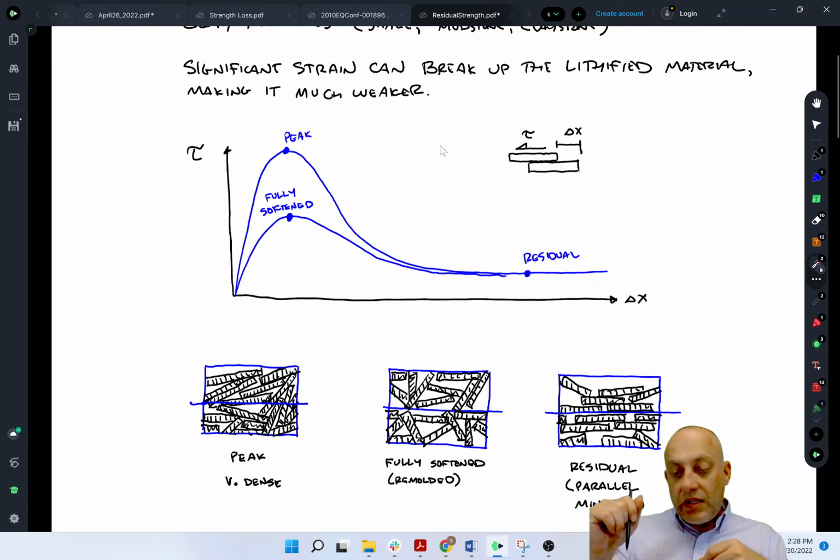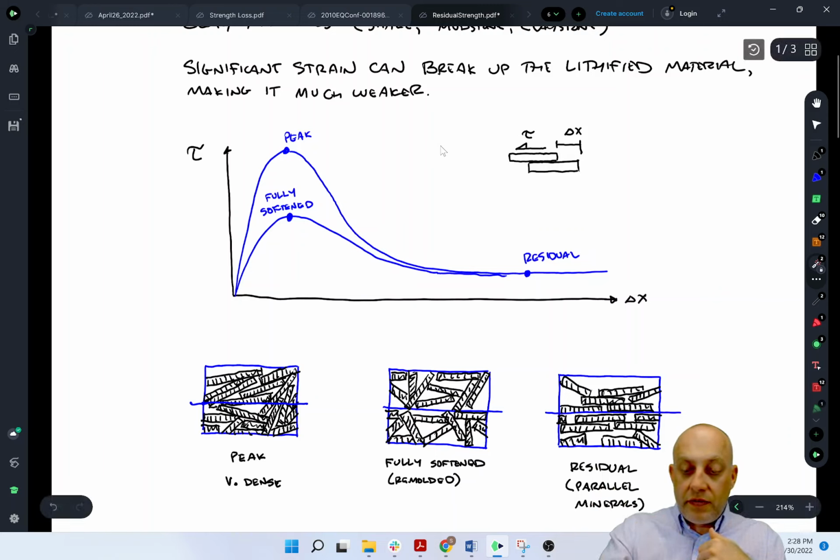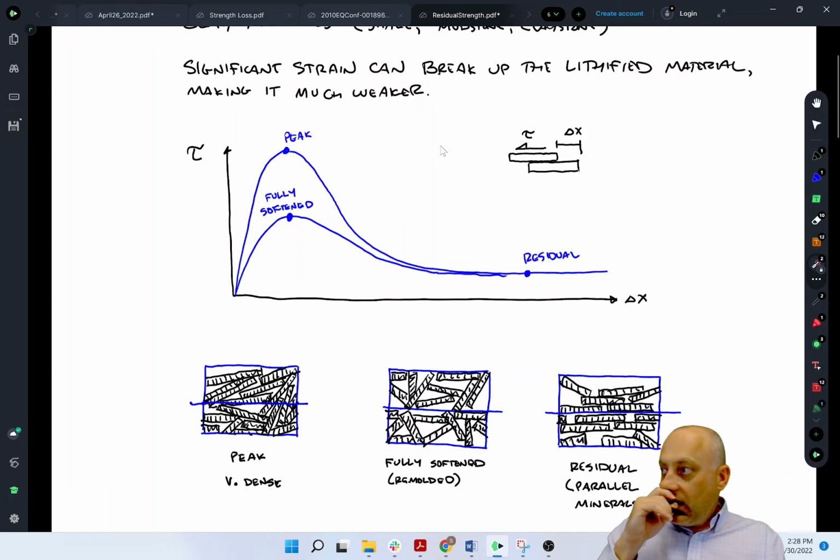So if you go to a site that's had a lot of deformation through a claystone soil, it'll look very shiny because a lot of light reflects off of these flat minerals. And so slickensides will be the sort of shiny material.